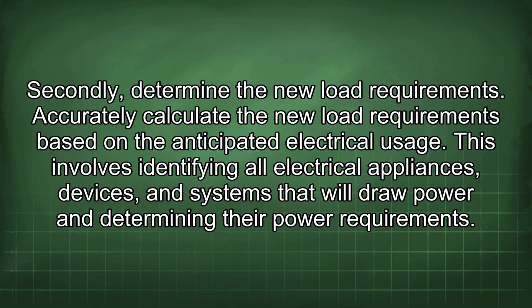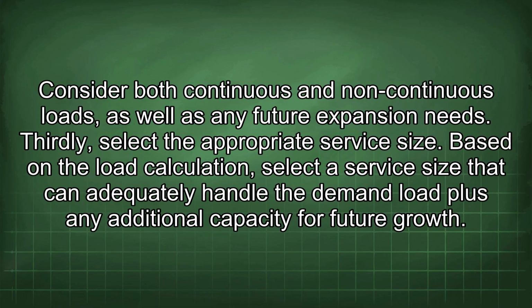This involves identifying all electrical appliances, devices, and systems that will draw power and determining their power requirements. Consider both continuous and non-continuous loads, as well as any future expansion needs. Thirdly, select the appropriate service size. Based on the load calculation, select a service size that can adequately handle the demand load plus any additional capacity